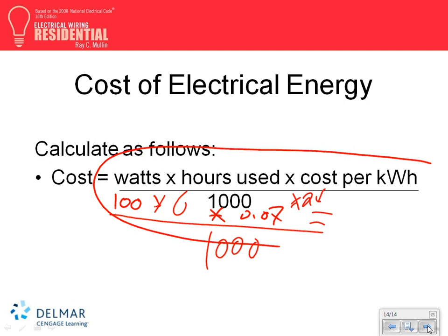There are two ways. Now how do you modify this? Well, you already bought this one for 5, so if you're going to add tenants here, you can still add up to six. When you want to add a seventh one, out of that whole building, you put a seventh over here, no problem, add another section to it, and then you put a disconnect right in here, between the wires coming in, for the whole building. That will be your main service entrance.